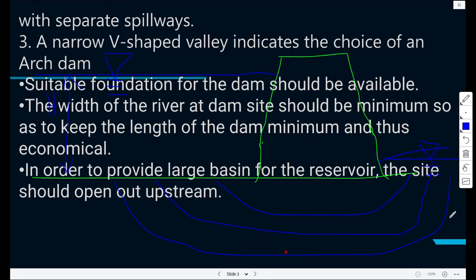So there will be some water, and it's difficult to avoid that. Under the dam, you need to control the seepage. Even though we know that's going to happen, we need to control the seepage to very, very low levels. Otherwise, the dam will be in jeopardy. That's why in the syllabus we talked about seepage through the foundation, but especially for earth dams, water will also tend to flow through the earth dam.